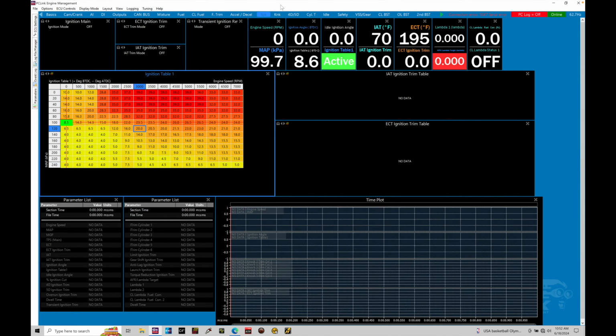An example of a pulse width modulated would be a Honda engine or a Nissan engine. They generally use a pulse width modulated type of idle control motor. If we're dealing with something like a Mitsubishi Evolution or a Toyota Supra, they're going to have a stepper motor and they function in a different manner and they're not pulse width modulated in terms of the control. We'll be discussing and breaking down the idle control and the specifics with the idle control motors in future training tutorials. But for right now, let's just jump into our file here and set up an idle control solenoid that's based around a pulse width modulated type of format so we can just see what this looks like.